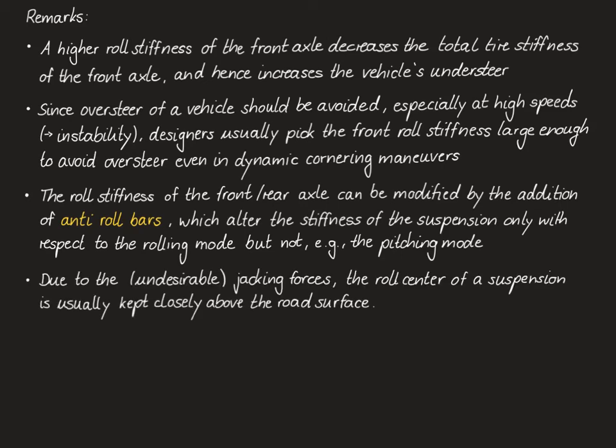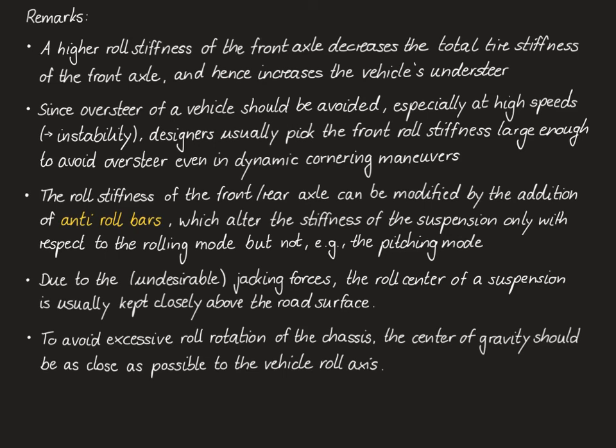Moreover, in practice, due to the undesirable jacking forces that were introduced earlier in this video, the roll center of any suspension is usually kept closely above the road surface. And finally, in practice, to avoid excessive roll rotation of the vehicle chassis, the center of gravity should be kept as closely as possible to the vehicle roll axis.